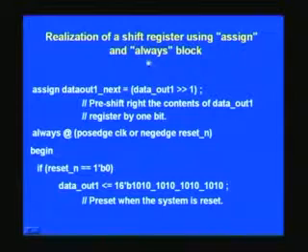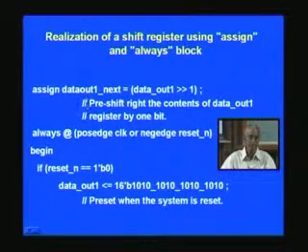We use once again an always block as such, and as usual we'll use assign so that we do the pre-computation, say in this case the right shift. This you are already familiar from our combination circuit. We are going to precisely use the very same thing. The shifting is actually done in the combinational, but we also combine a sequential here, so that the real system picture will be this combination. And here data out 1 is shifted by 1.